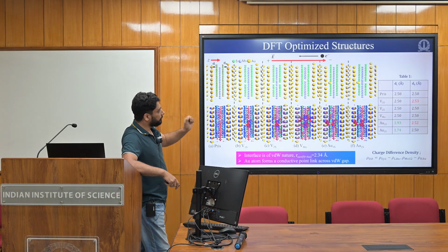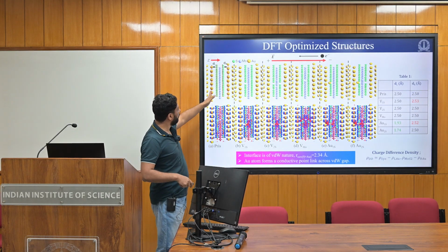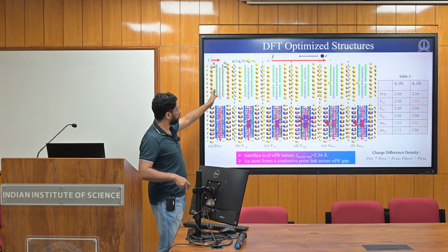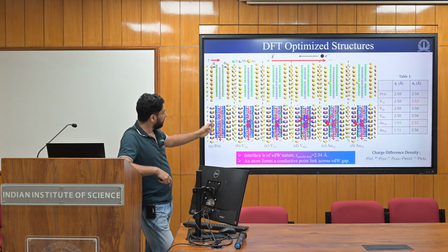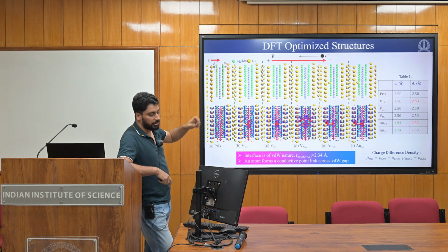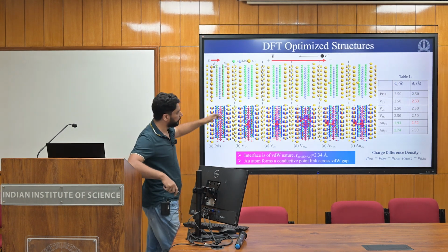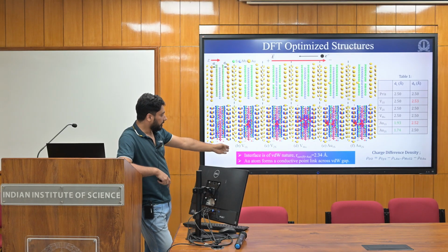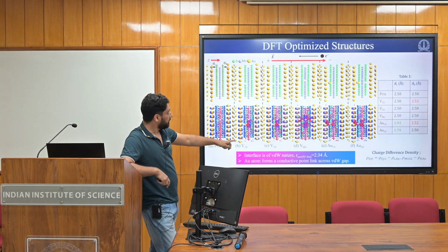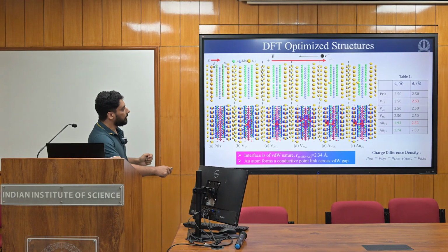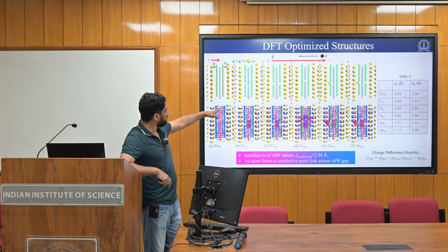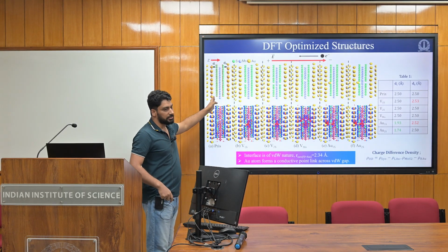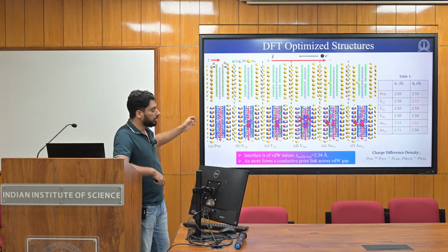Now from here, what I observed first was how the gold is basically interacting with the sulfur of this MoS2. So for any 2 atoms to make a bond, the bond length between them should be less than the covalent distance. So if you see the covalent radius of sulfur and the gold, it's around 2.34 angstroms. But if you see the interfacial distances, they are more than that, around 2.5 angstroms. So which shows basically the nature of the contact here is of the van der Waal type. It's not making any covalent bond.